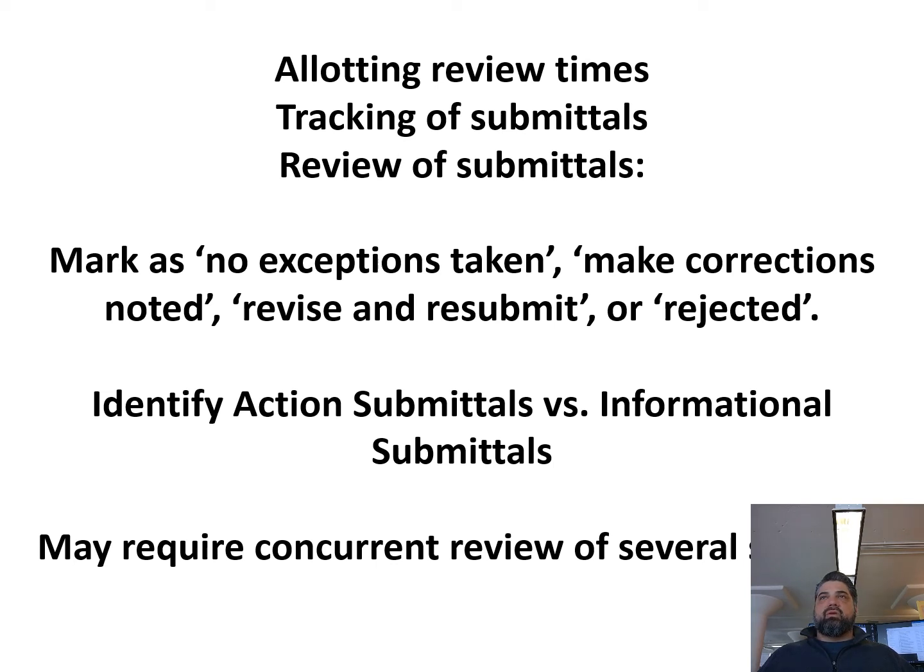So you need to make sure that you allot yourself time during construction, because you don't always know when they're going to come in. And so make sure you allot yourself time to be able to review those when they come in. You need to track them, right? It's really important that you know what has come in, when it came in, what action you took, and when it went out back to the contractor.